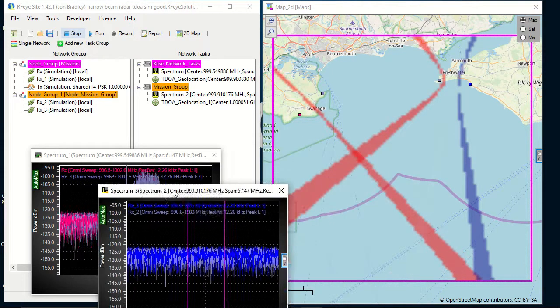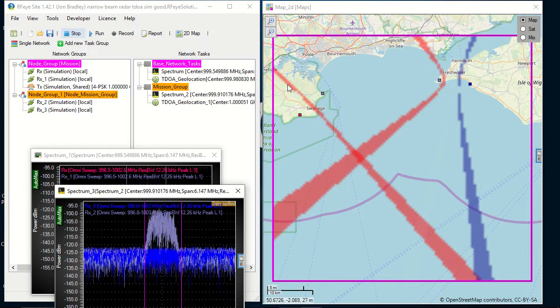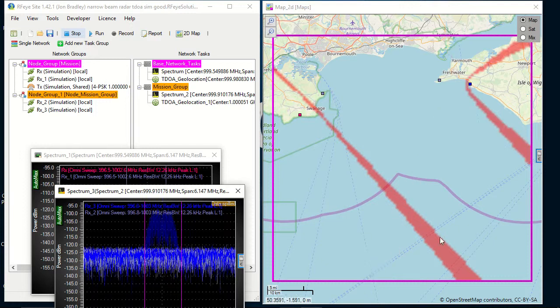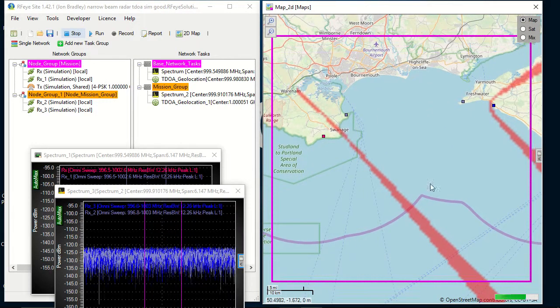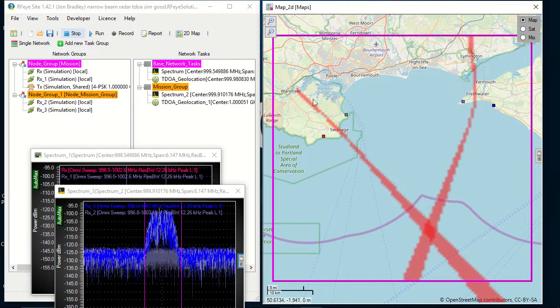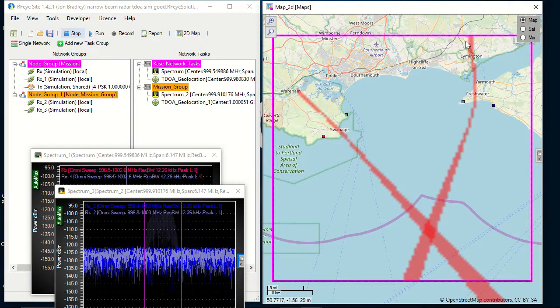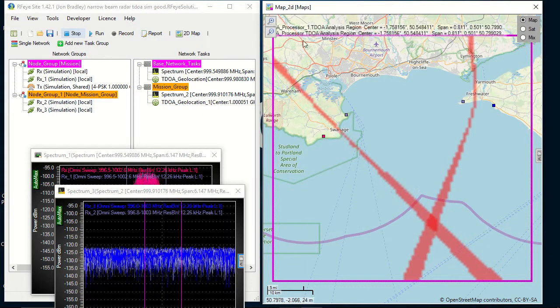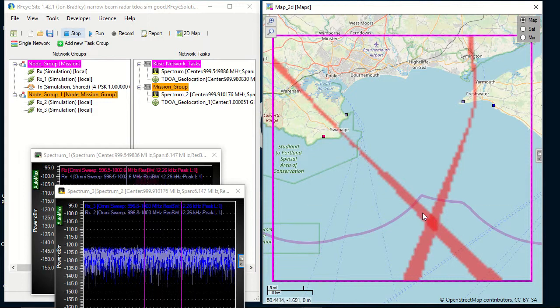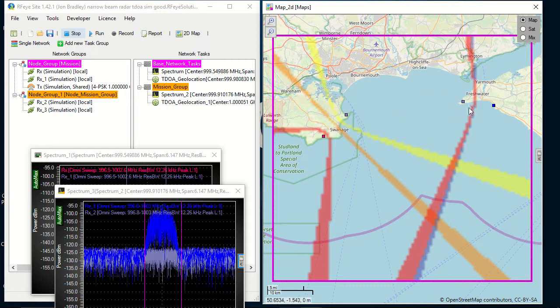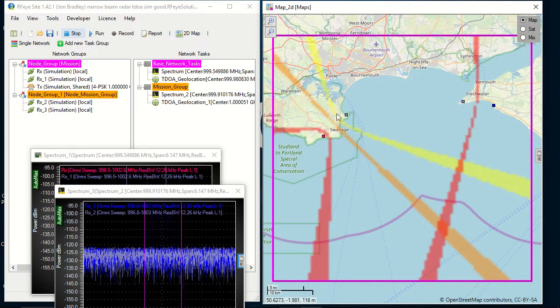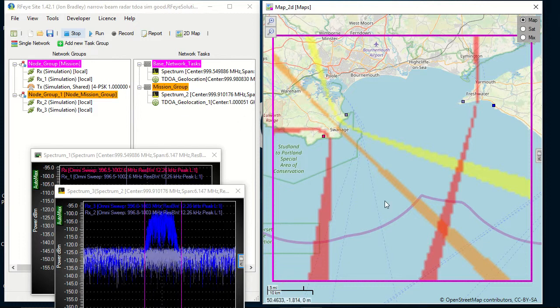And what's happening is the TDoA engines are drawing the isochrone, in other words, the potential position of the transmitter, and then storing the data on the screen. Now, the interesting thing, of course, is where those 2 isochrones cross each other. This is now the location of our transmitter. You get a little bit of intermittent things as the signal to noise isn't great, or the averaging hasn't quite worked out. We could go back and play with the averaging here.